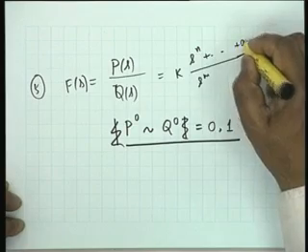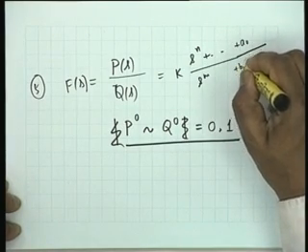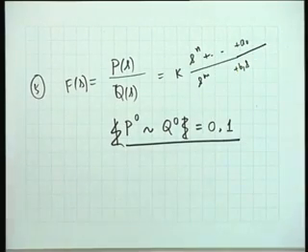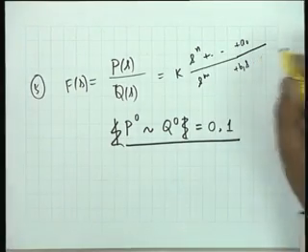What can you say about the lowest powers? Suppose the constant term here is a0 and there is no constant term here. Suppose the first term is b1 s. Is this permitted? Is it permitted to have b0 equal to 0? Yes. Suppose b0 is 0, then we shall have a pole at the origin. If a0 is 0 and b0 is not 0, then there is a 0 at the origin.